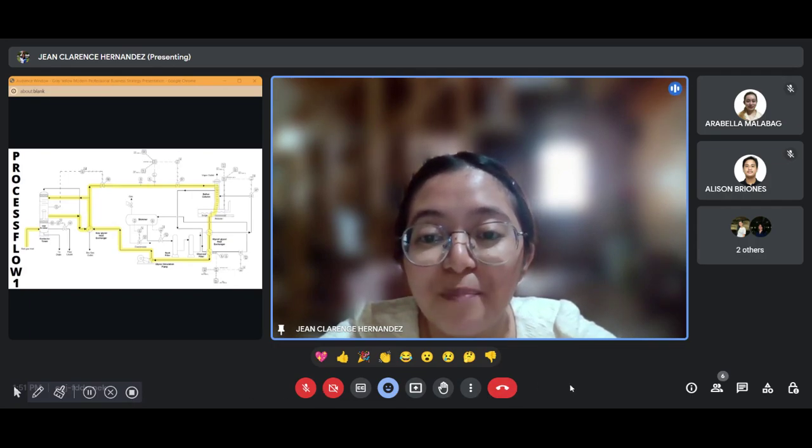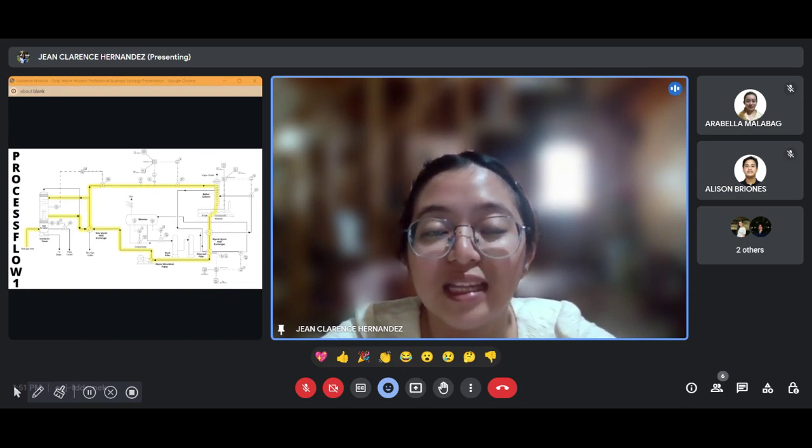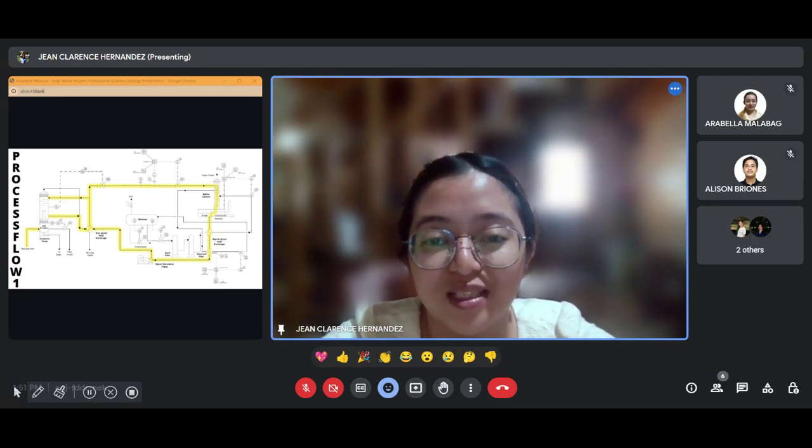After passing through two glycol heat exchangers, the lean glycol is returned to the system by the glycol circulation pump. The cycle persists as the lean glycol moves through the gas or glycol heat exchanger, ultimately re-entering the contactor tower. This repetitive process effectively ensures the conversion of natural gas into a dry state, meeting specified requirements.